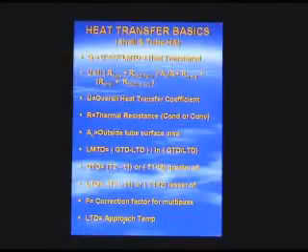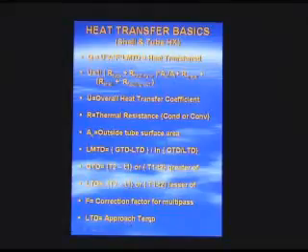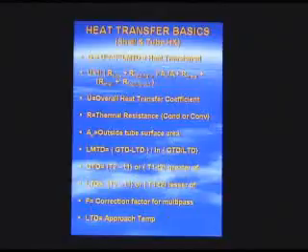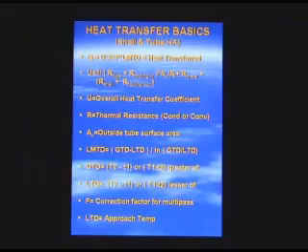The lesser temperature difference you could also consider to be the approach temperature, which somebody asked about at the last meeting. That basically indicates how close you can bring the two streams together and have effective heat transfer. For shell and tube exchangers, that is typically on the order of 10 degrees or maybe a little bit less. Plate and frame exchangers can get down to approximately 5 degrees or a little bit less. With air-cooled heat exchangers, your process stream can approach the inlet air temperature by about 20 degrees.